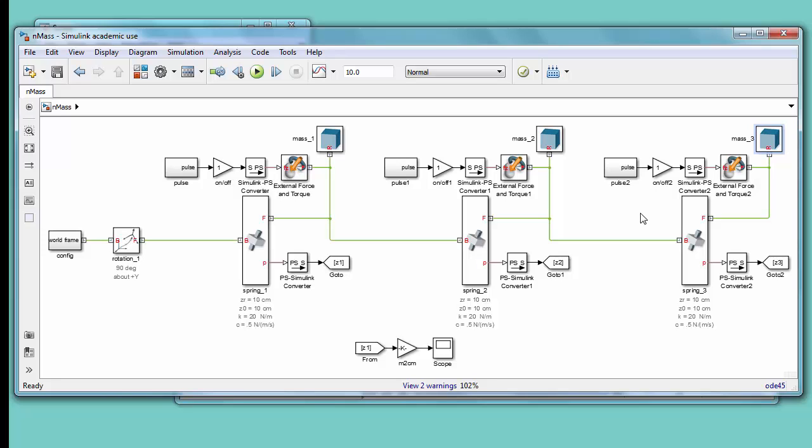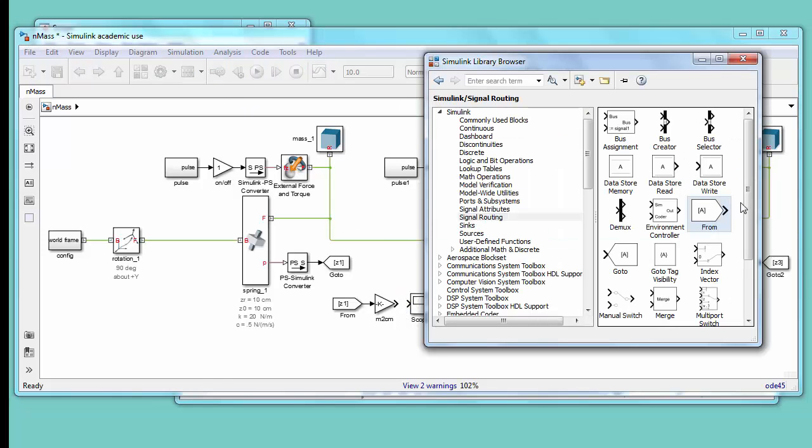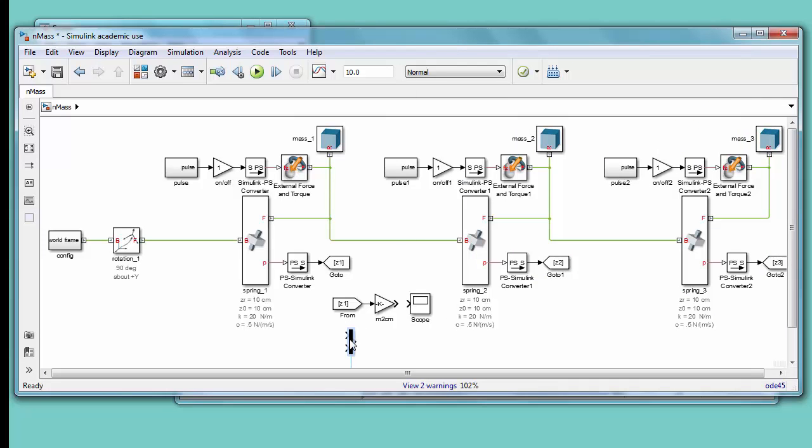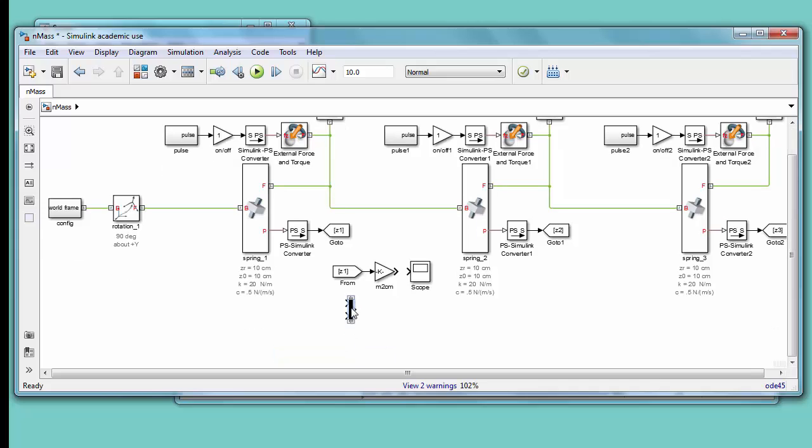But we can easily turn those on and off with those little gain blocks that we added. So we'll play around with that. But first, let's get all of these nice position outputs into a single scope. We could have multiple scopes, but then you'd be clicking around to see who's who. So we'll grab a mux block. There it is. Increase its dimension to 3.